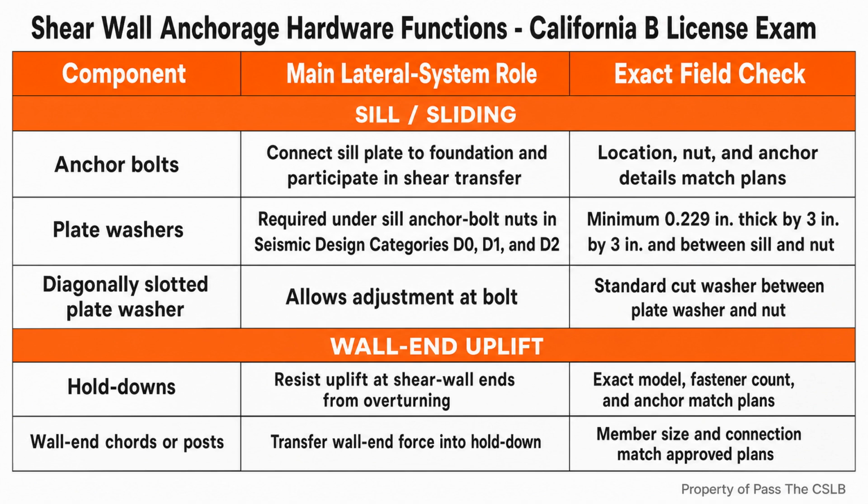Structural supervision does not excuse unsafe framing methods. Effective July 1, 2025, employees doing residential type framing work must have conventional fall protection when they are 6 feet or more above the lower level. The covered work includes activities such as walking top plates, installing joists, setting trusses, and placing sheathing. The old 15-foot residential framing threshold is no longer the current rule.